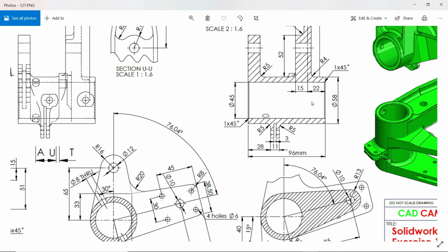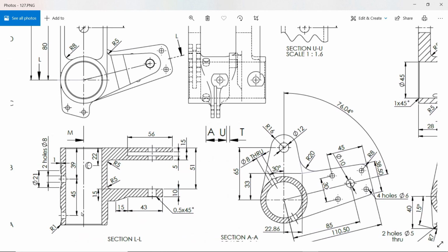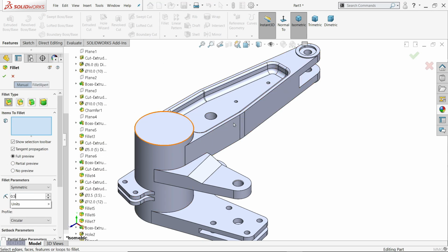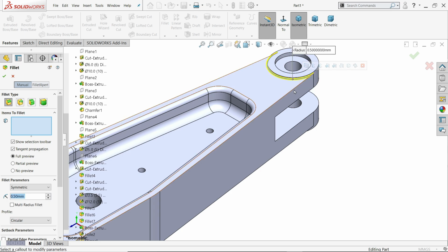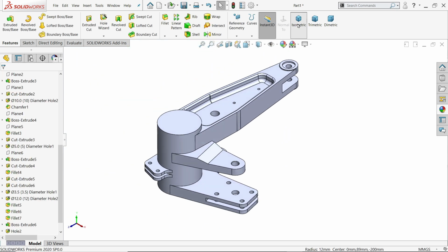and we will create this center hole 45 diameter, 1 chamfer at both corners, 1 millimeter, and there is a radius. This corner R1. Activate radius 0.5. We forgot to mention this. Okay.